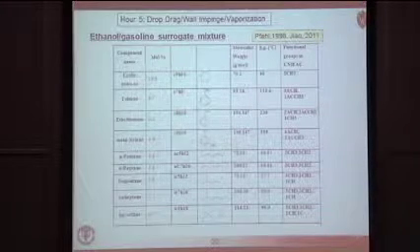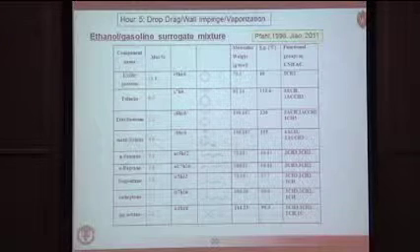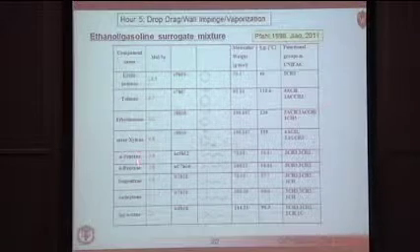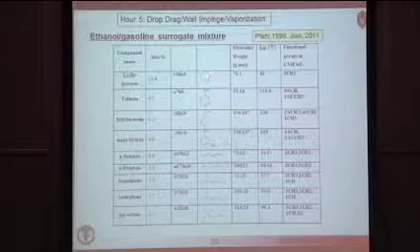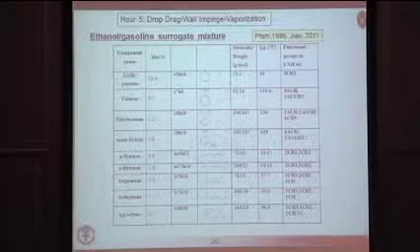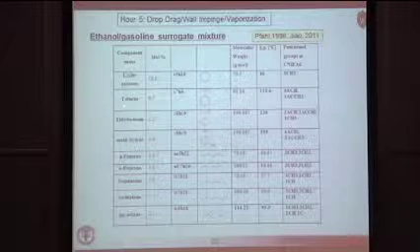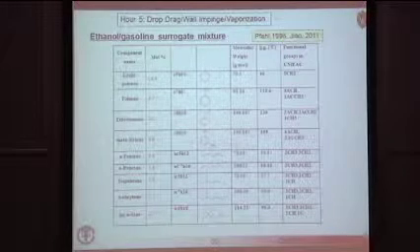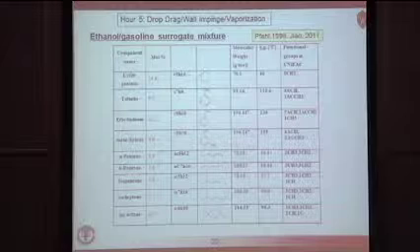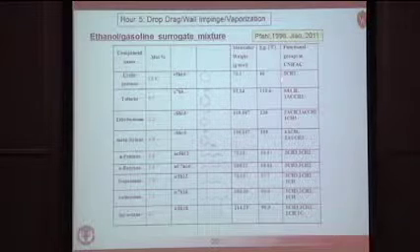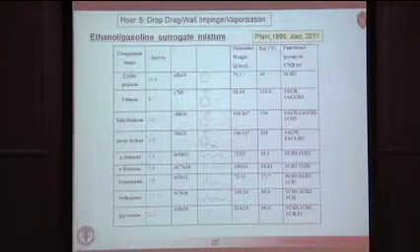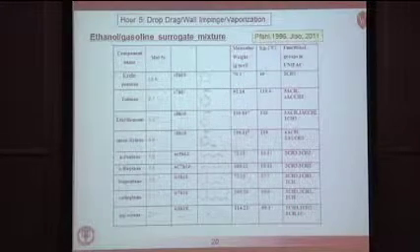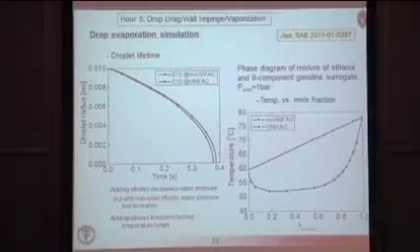We have gasoline represented as cyclopentane, toluene, methylbenzene, xylenes, and so on. And little pictures of the molecules. So this is kind of a 10 component gasoline. If you look at the functional groups that appear in the UNIFAC model, they are sort of listed here. And then you would apply that as part of your calculation.